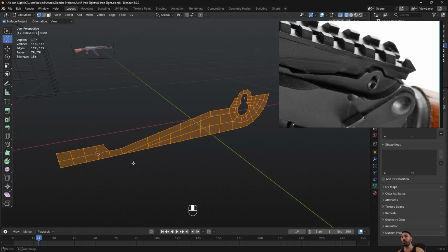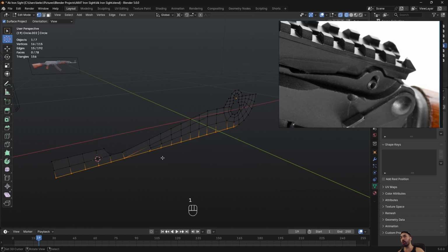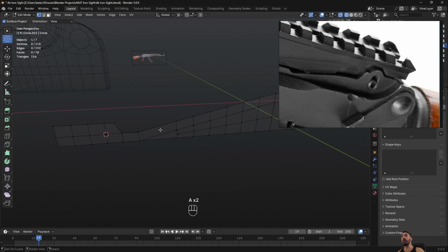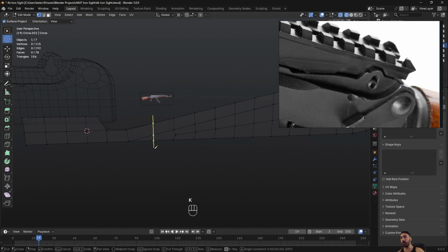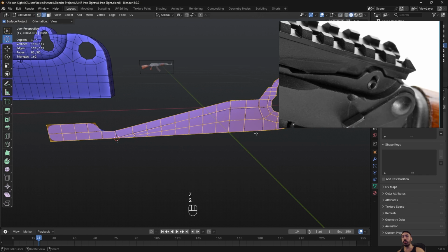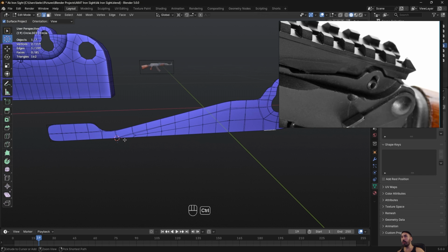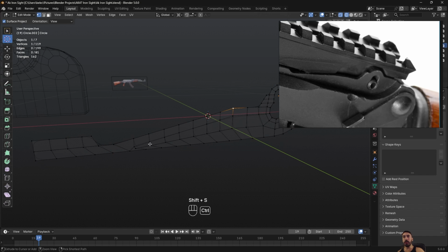Now let's move on to the next part, which is going to be creating this little surface over here on the front. So before we do that, first of all I want to make sure that all the edges down here on this lower segment are roughly the same length, and as you can see we have an edge over here which is much longer than the others. So I'm thinking it would be nice to just do a knife cut over here on the z-axis, do the loop cut thing here one more time, join it with this one, and now it's a little bit better. We could use our loop tools to take this all the way to make them completely even and straight, Loop Tools, Space, but as you can see then you got a lot of cleaning up to do.